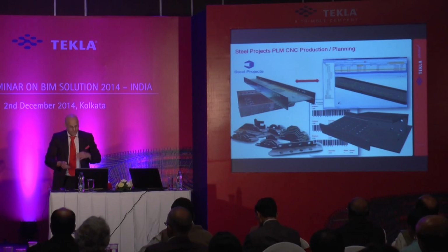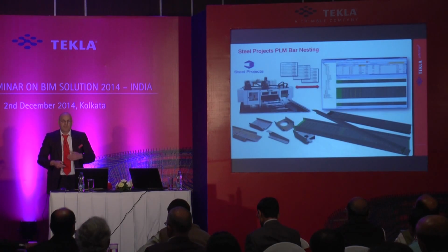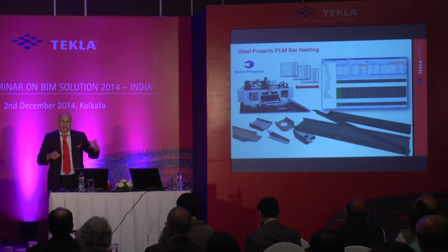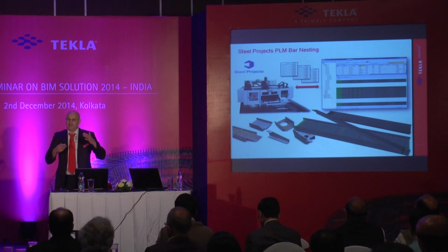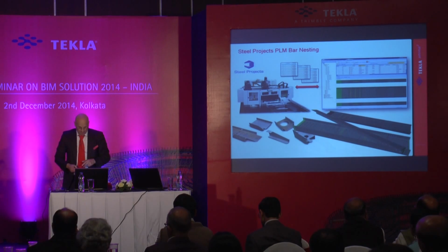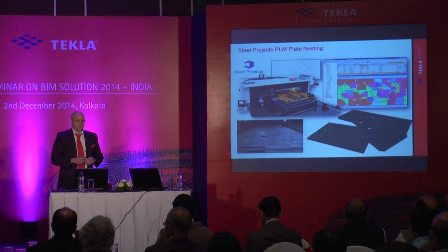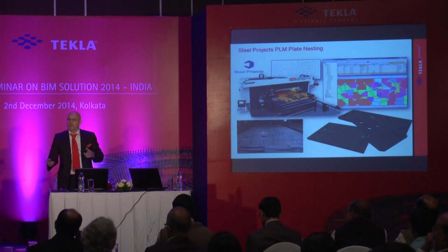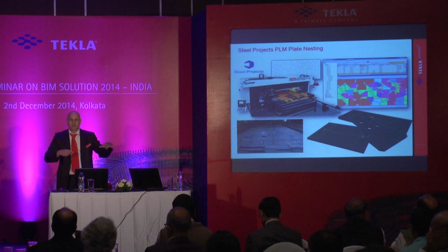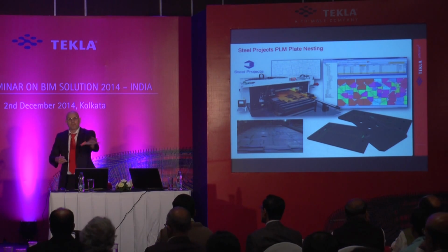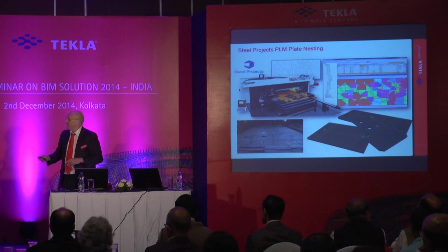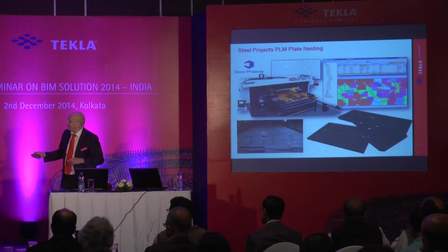Okay, so that's that. Once the pieces are within the software, they can optimize those bars for bar nesting. Now, if you've already got bar nesting software, we can integrate to it. It doesn't matter whether it's Strumis, FabTrol, it doesn't matter to us. We can link into it and do that for you. Then there's also the plate nesting. If you have plate nesting software, we can link to that as well. You don't need to do any work, just take the elements from Tekla and it'll drop into your existing plate nesting system. This then will do optimization of plates, again it does the layout, marking, all that kind of stuff, and finally links down to your machine.